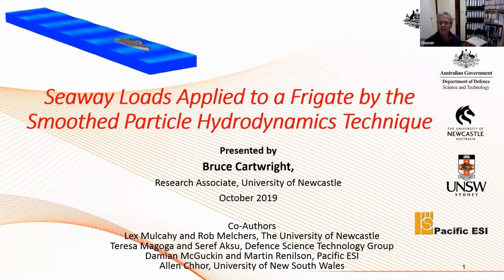Yeah. Bruce, thanks very much for a great presentation. Very, very clear indeed. And massive progress since I last heard from you, must be a decade ago. To start baby steps of validation, have you got validation of, say, pitch and heave RAOs against either tank test data or strip theory or some other established method? I thought Maestro would have conformed to one of those. Well, you've done bending moments against Maestro, but I just haven't seen pitch and heave RAOs.